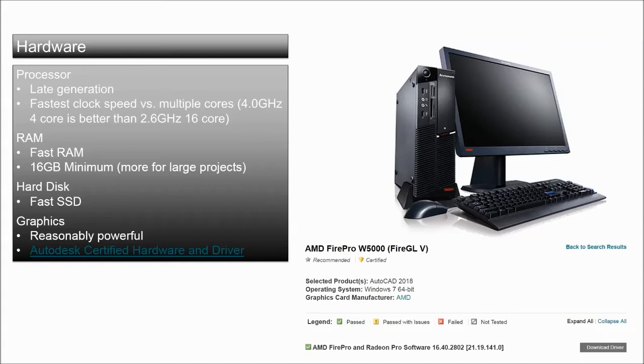It can be important to ensure that you get a graphics card and the driver from the certified list at Autodesk.com. The image on the bottom right of your screen where it says AMD FirePro, I just grabbed that arbitrarily from the Autodesk website. Essentially, Autodesk tests many of the graphics cards and their drivers with their Autodesk software.